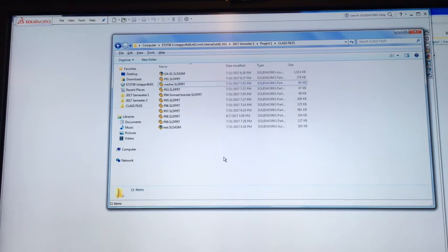Okay. So what I've done is I've just renamed them in Windows Explorer. When you open your files, or when you create an assembly, every file that you add to that assembly has a reference. It's referencing back to its location on your drive, or someone else's drive, or USB, or whatever, and what that file name is. So when you save your assembly, it remembers all that information.